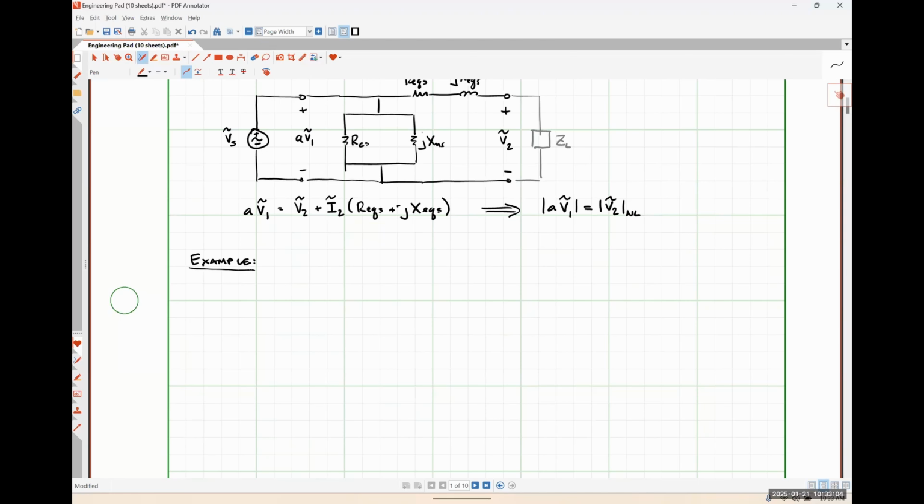So we should expect to see a relatively large power draw at that time. And we wouldn't want the secondary voltage to fall because of that increased load, that would literally cause blackouts and things like that. So we're going to talk about the voltage regulation. It tells us how good of a job a transformer does at maintaining that secondary voltage under specific conditions.